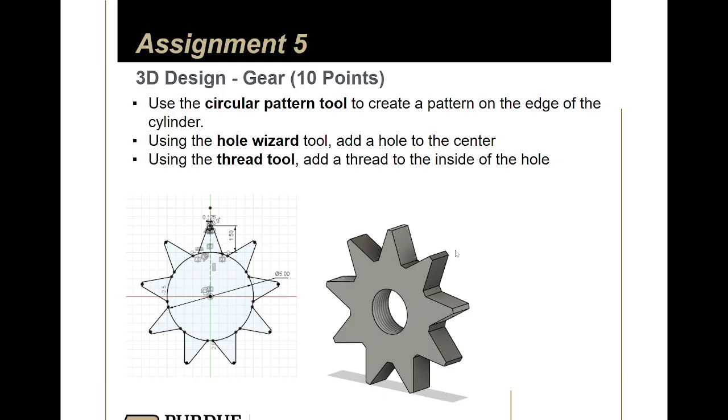But if you just have some kind of sketch and extruded cut, Fusion won't know if it's actually something that needs a drill bit or not, right? Even though it could be a circular hole, Fusion could be like, oh, that's a pocket, not a hole. So I'm going to use an end mill instead of a drill bit. And then if you do that, it could take a considerably greater amount of time, which makes it more expensive, or it could just be straight up wrong, right? So using the hole wizard sets your machinist up for success. So that's why it's a really good idea to use it.